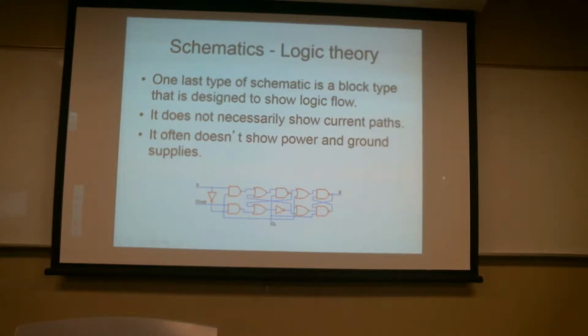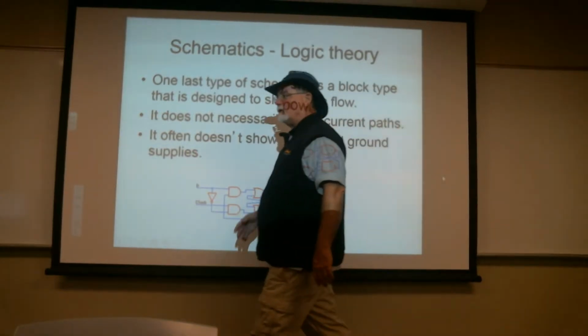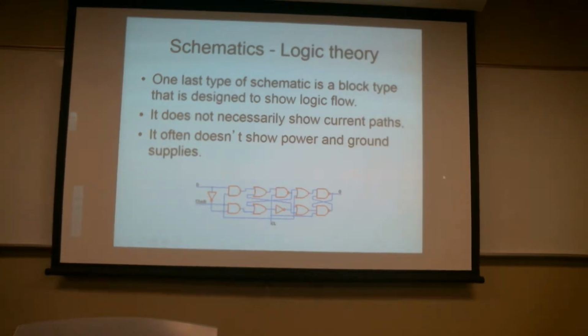But on the other hand, for the designers of this product, it was easy to buy an 8-bit register that's a bunch of these little logic gates glued together in a single chip. Use that to drive a bunch of relays, and then the big power relays are what turn the banks on and off. Meanwhile, it was programmed that if you do one set this way, it shuts them all off. So that was a simple use based upon readily available chips. They didn't have to program anything. They just bought the chip, an 8-bit binary counter.